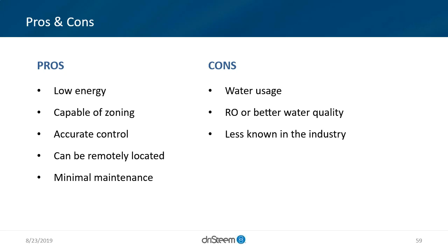So that does require more water usage. The RO isn't 100% in, 100% out as permeate. There are different recovery rates, typically around 75% recovery. So for every 4 gallons you put in, 1 gallon's going down the drain. Same with the evaporation efficiency. And as we notice throughout the industry, adiabatic technologies are growing at a faster rate than the typical isothermal systems, but they still don't have the history that the traditional systems have.